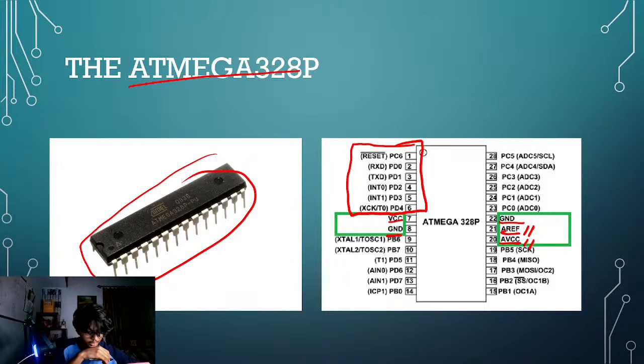Is it like a flip flop which will store 0 or 1, which will change how the pin works? Yeah, that's exactly right, actually. And we can change the flip flop with pinMode in the code. You're very close. But pinMode dips into Arduino. The Arduino is an abstraction of the Atmega. Atmega, you program it using very bare metal C. Okay, you go into the register level, you change registers and you do it.